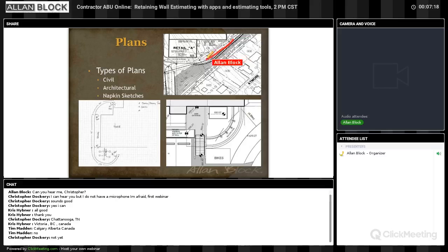This is our wall here, this curved line up here, and then you can see there's some contour lines or grading lines below, and that's something you're going to often see on the grading plans or civil plans, along with, for the retaining wall, top wall, bottom wall callouts, and that sort of thing. It's just going to have the most detailed information. Sometimes there's a lot going on and it's difficult to find the wall immediately, but it should be the best place to look if you're trying to determine the geometry of your wall.